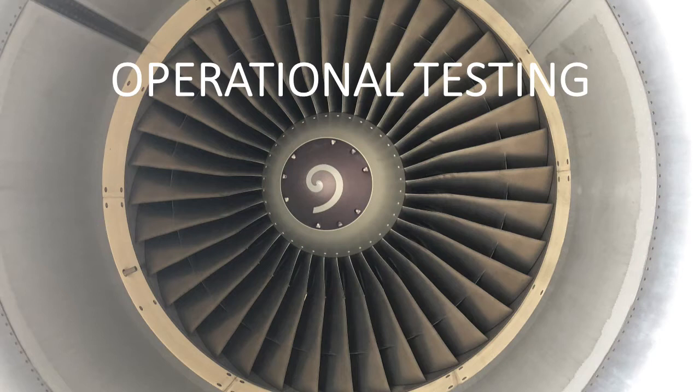All right. And on the operational test, you're going to see different things on here, but of course you want to follow the aircraft maintenance manual. You do want to make sure that the circuit breakers are closed, but you need to read to see which circuit breakers need to be closed. So do pay attention to what it says in the AMM, the aircraft maintenance manual, about that.